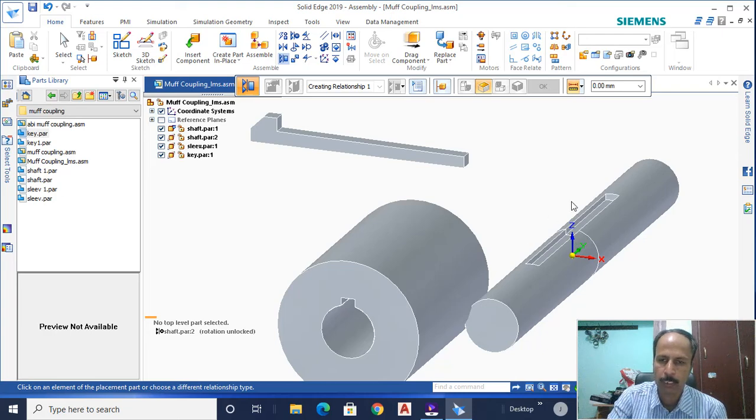Now I simply rotated and then added it, but you can do that. Okay, let us see. Click this and then click this. They are now properly aligned using this relationship, that is align faces. This is the align faces toolbar. So using that, it will ask for the first face and then it will ask for the second face. I did that.